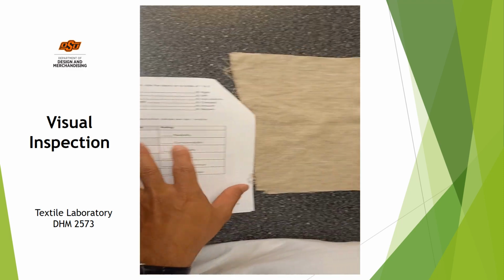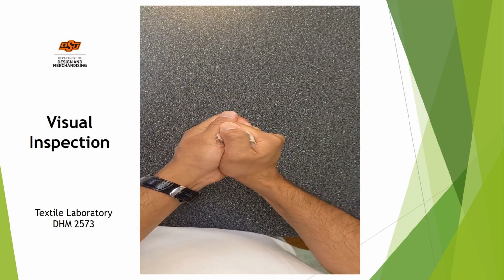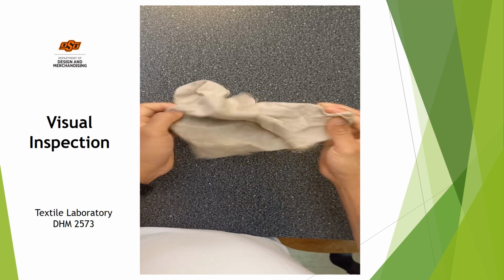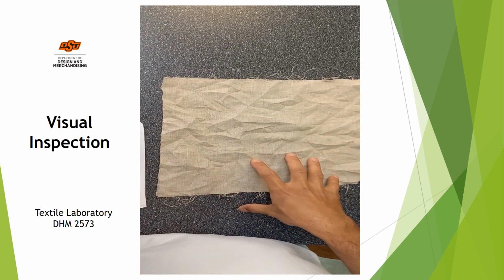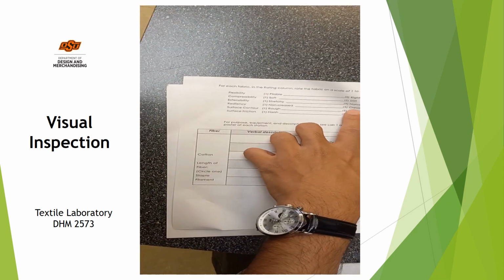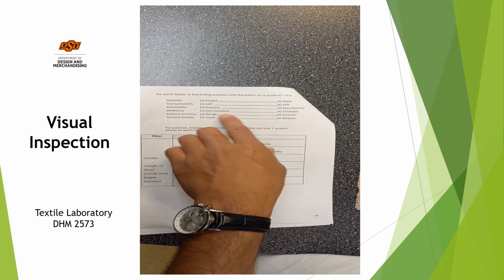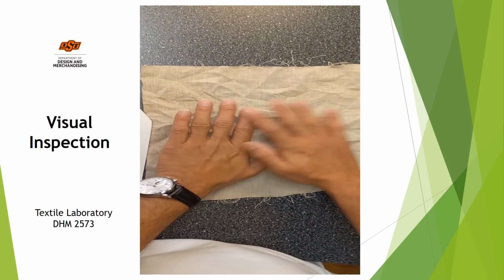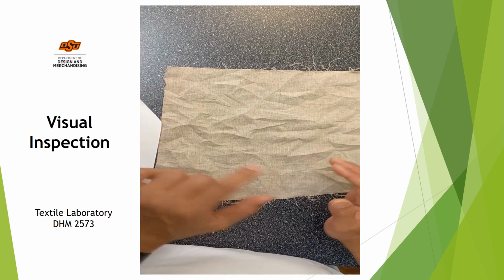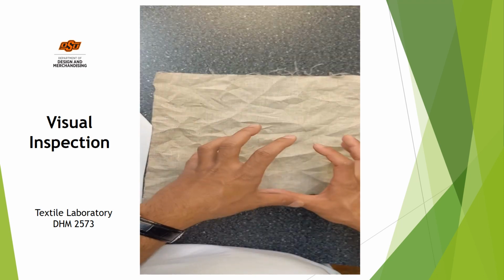So resiliency means, if I apply force, if we make a crease and then make it flat, do we have any crease mark on top of the fabric? Okay, if we have a lot of crease marks, then the rating will be 5, very creased. But if the fabric is totally non-creased, and after that we don't see any crease mark, then the rating will be 1. But in that fabric, what do you think? Can you see any crease?